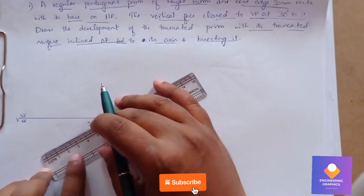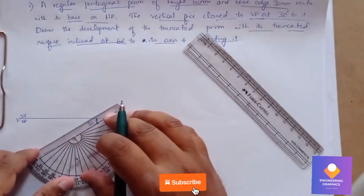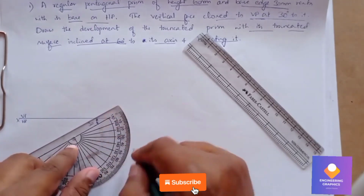Take 30 mm from the reference point. Take the protractor and mark 72 degrees. We know the external angle of a pentagon is 72 degrees.